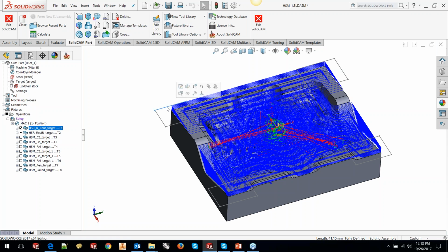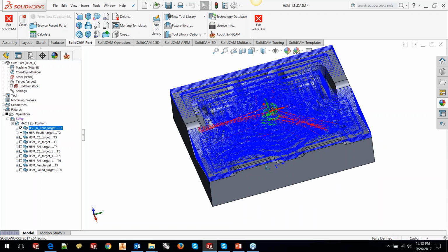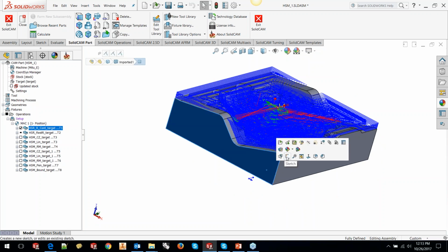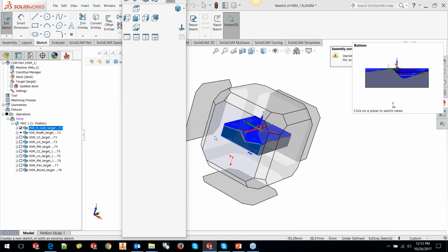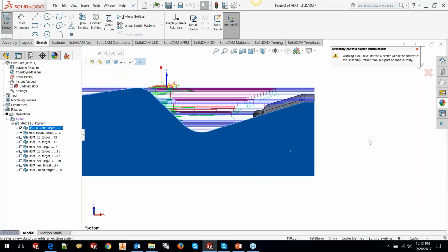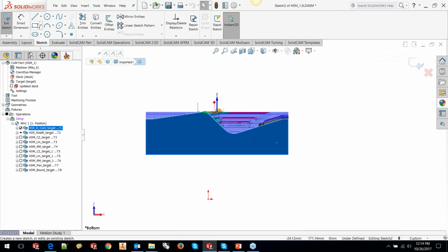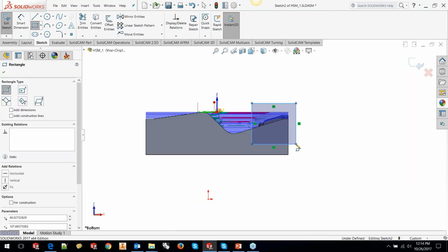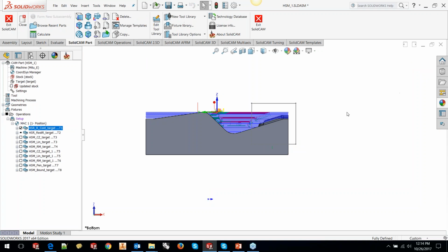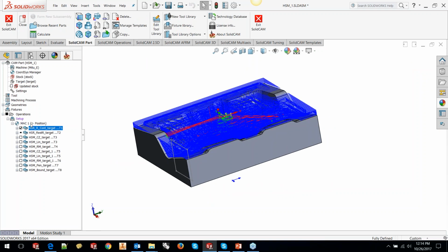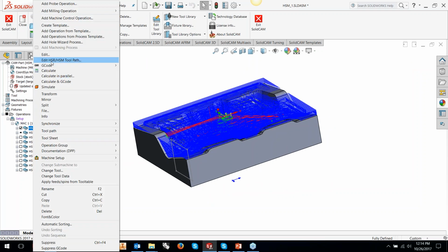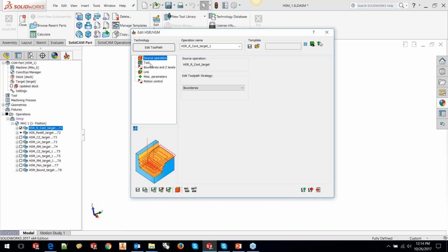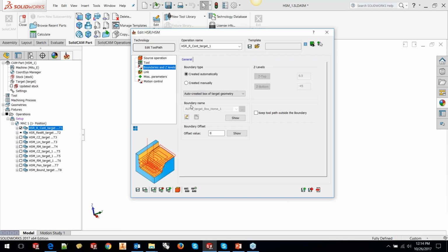Now, while we were doing this function in SolidCAM, I realized that you could actually perform the sketch in any plane. For example, I'll go to the side of this, on one of the sides, and I will make another sketch here. Okay, and I could do the same editing. For example, I'll define the boundaries again.